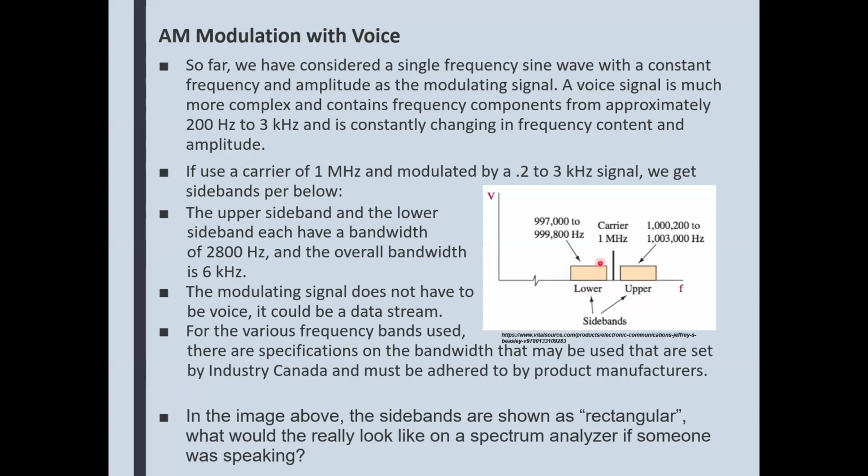And we want to have certain ways. So when we have the upper and lower sidebands, they contain the same information. So we can cut one of them, upper sideband or lower sideband, and you could have more channels, because in order for the channels to not interfere, they had to be separated by a certain distance to have some breathing space, to not intermod into each other, not to interfere with each other.